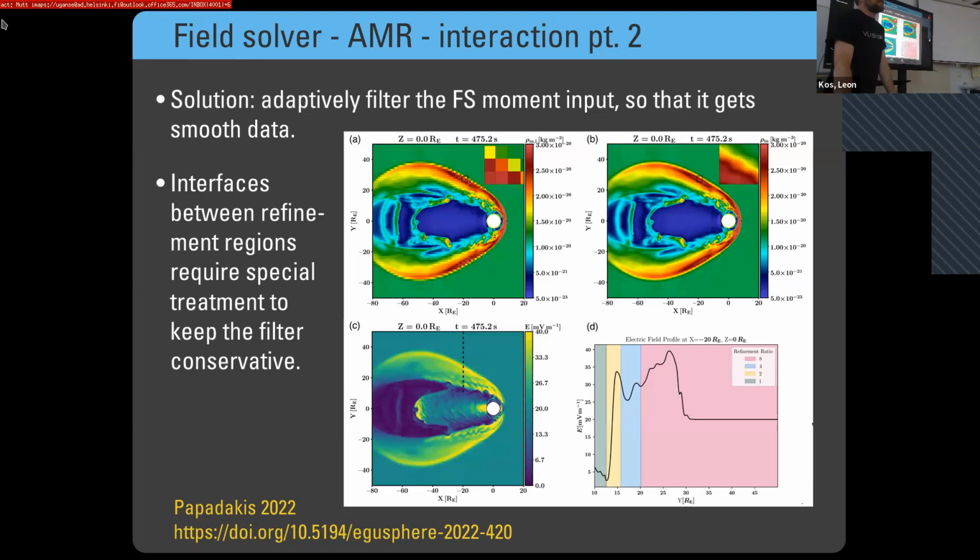The way I understand this is that in the coarse region, you have a coarse representation of fields, and in the fine region, you should have a fine representation of fields. Yeah. And you can calculate them separately because they're parallel. So why would you need a fine mesh in a coarse region? Because for our field solver, we did not bother with implementing an AMR version. The field solver only has one resolution, and it's so fast and vectorized and parallelized that we can afford to also run the field solver at high resolution here.